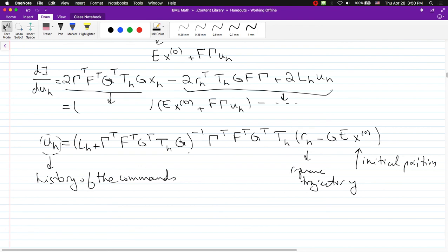Okay? All right. So these are the class of problems called open loop control. And they're not very realistic ones because you never want to just send some commands and have nothing feed back to it. And so the interesting problems are the ones that have feedback. And then the problem becomes much more interesting because you say now, what's the policy that I should have? So you don't know precisely the commands you're going to have in the future. You're going to have a policy that says, if this is the feedback that I got about my state, this is the action that I want to do.